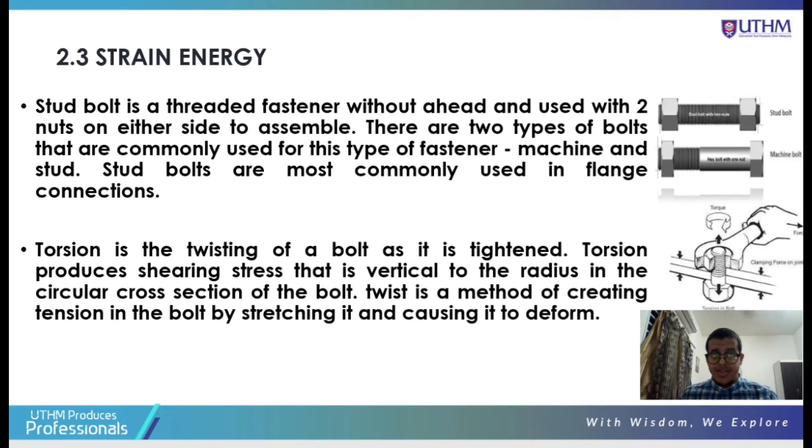Stud bolt, a threaded fastener without a head, is used with two nuts on either side to assemble. There are two types of bolts that are commonly used for this type of fastener, machine and stud. Stud bolts are most commonly used in flange connections.